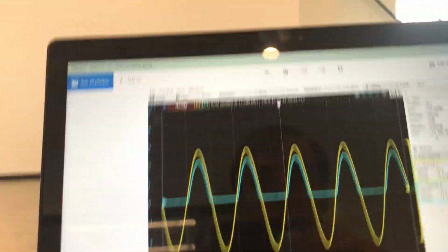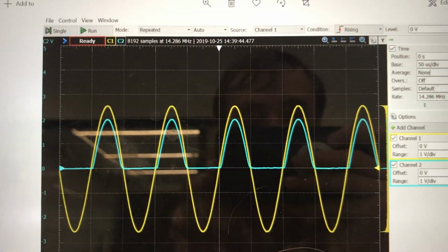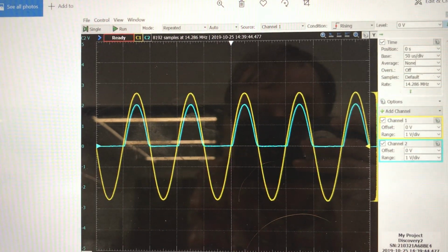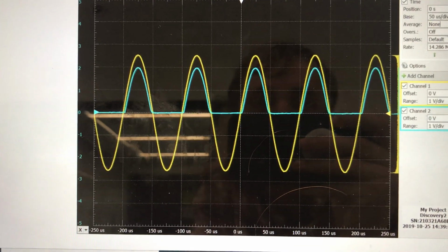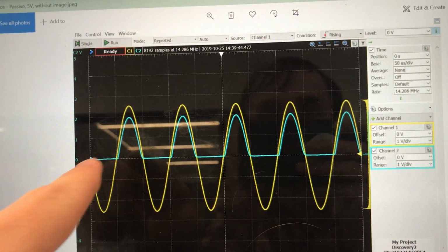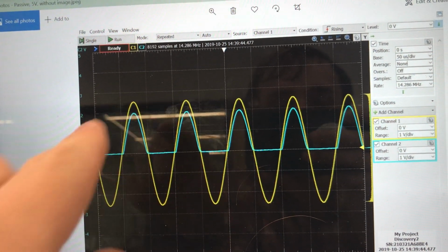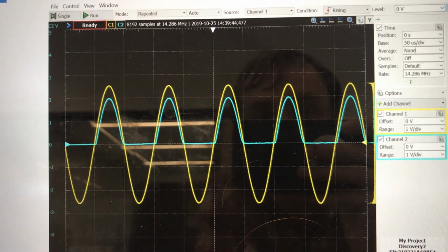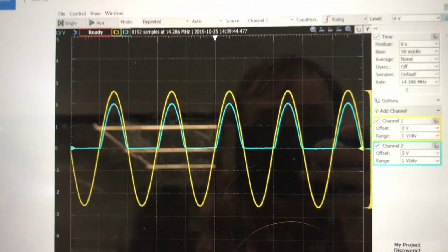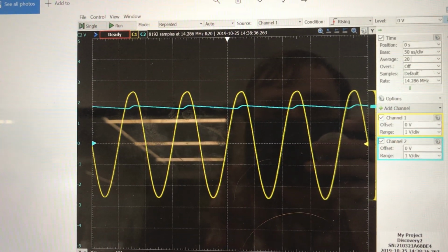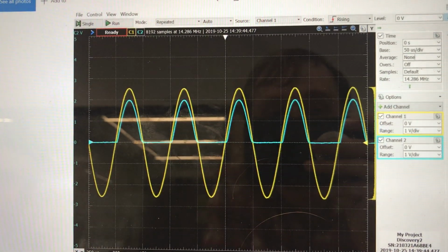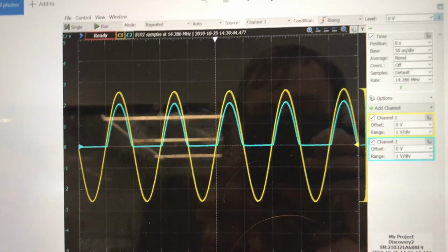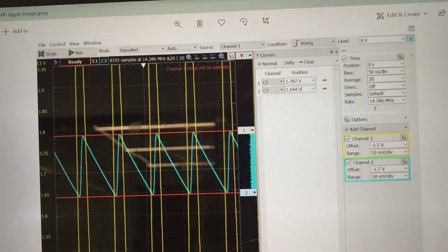And then we have the waveforms for part 2. This is when we used 5 volts input to the passive half-wave rectifier. You see a little voltage drop from the input to the output, and you only see the output voltage when the input is positive, because a half-wave rectifier only rectifies half of the wave. This was without the capacitor, so there's no ripple.